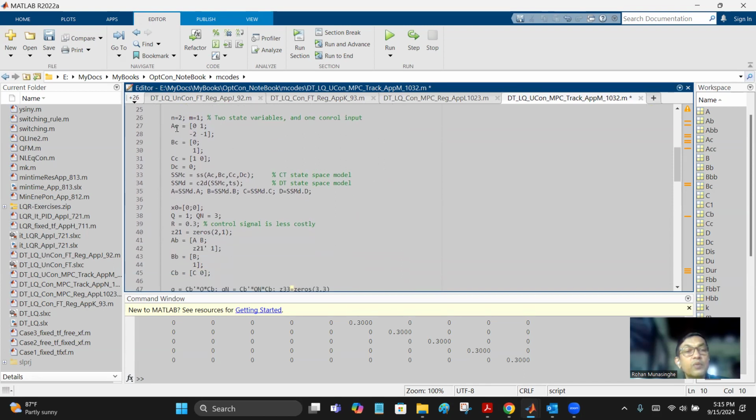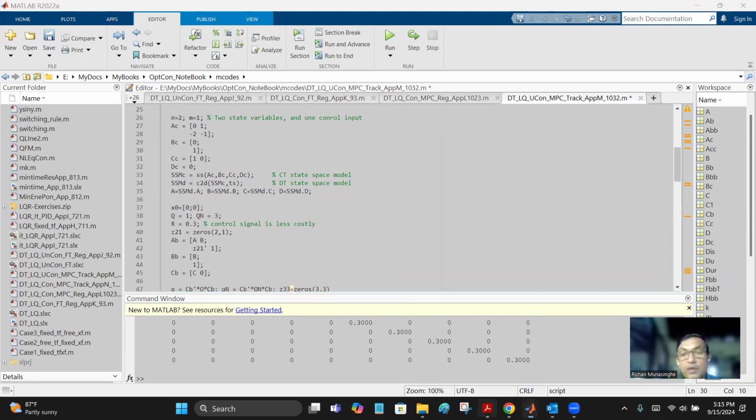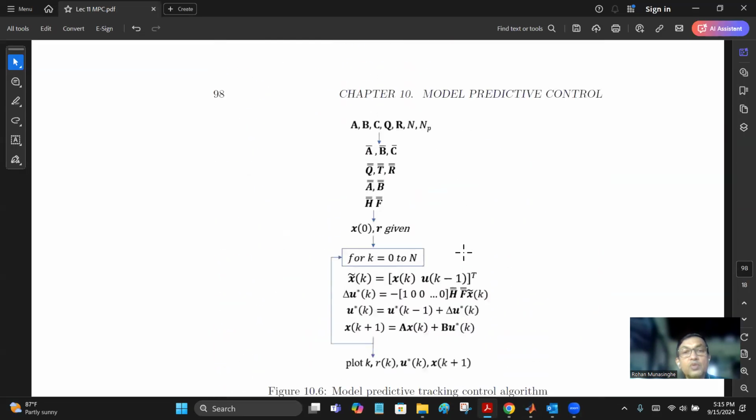I want to bring you over here. Yes, A, B, C. This is the plant system matrix. B is the drive matrix. A, B, C, D, right? Because in your algorithm, you need these to get going. For a particular plant, A, B, C, then Q and R are the cost for state and the cost for the control, like that, which should be given.